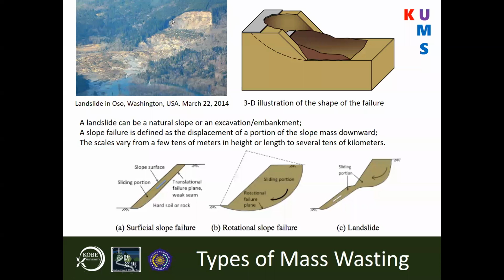I talked in that book about the Oso landslide, which is here. When you look at the landslide, you have the typical crown, and you can see the area where the landslide has gone down, with the toe and the foot of the landslide right there. In that case, you see the sloping surface is a bit curved like this, and that's how it went down. You can see the top part here, with the crack level. You can still see the top, which is right there, and all the rest of the material that slammed down.